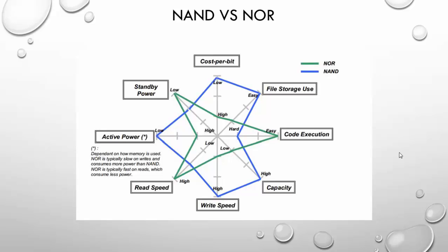NAND flash has become an attractive alternative for the data storage aspect of today's cell phones because of its high speed write and erase performance as well as its low cost per bit. As a result, designers of memory subsystems in portable electronics are now using NAND in some traditional NOR based applications. For today's full-featured cell phones, many designers are utilizing memory architectures that combine NOR with NAND for data storage, or they are using NAND as the primary flash memory in combination with low power DRAM, in which the program code can be shadowed and run. In either case, the different types of memory are frequently stacked in a multiple chip package to create a single component.